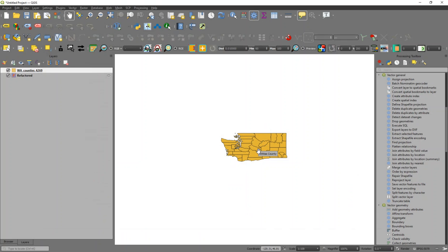So what I would recommend you do is save everything, shut down QGIS, start it up again, perhaps turn off some of your internet tabs, shut your computer down, restart, and try that transformation again, and it should work. Okay, so anyway, you can change your project CRS right here, and it should change your view of your data.